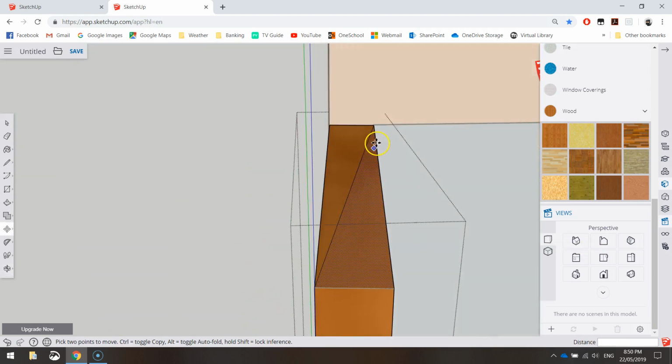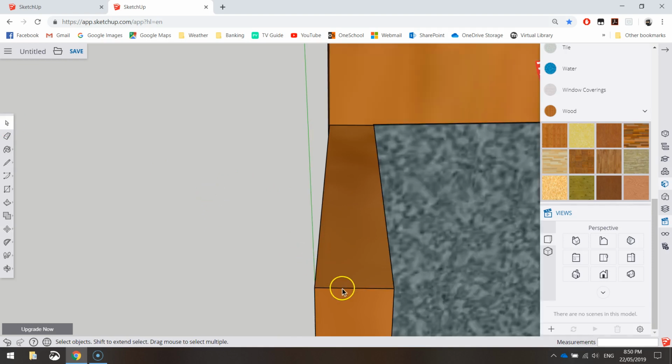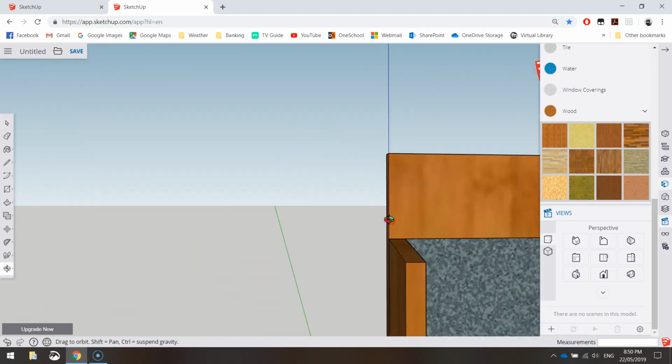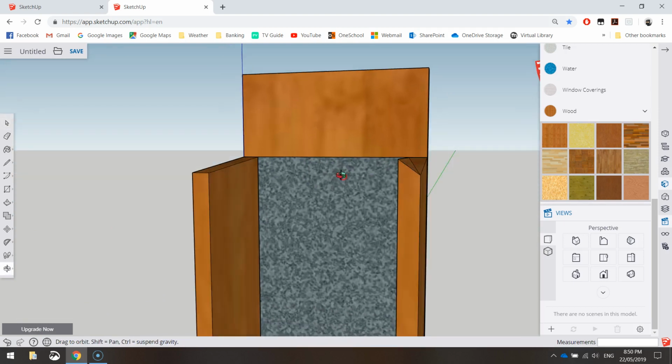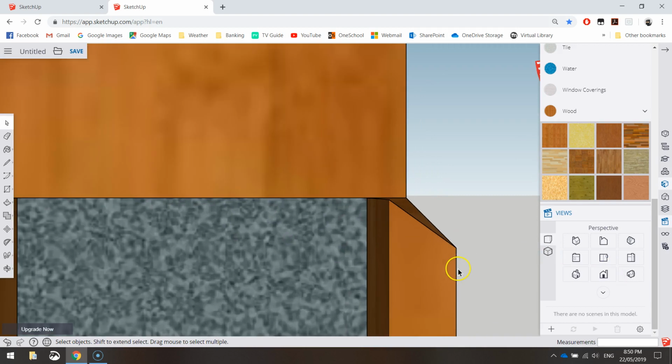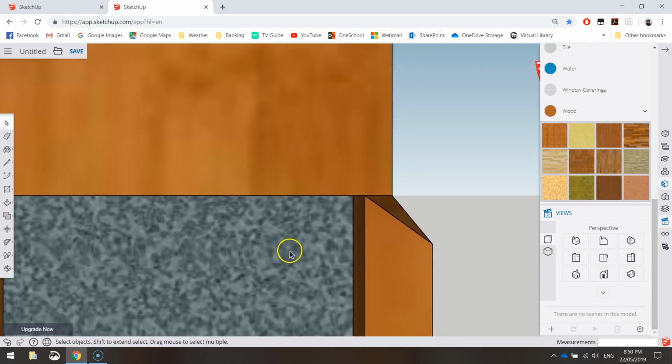There will be a black line running across the top of that you can just click on with your arrow and press delete. Don't need that. Click outside of your shape. If you want, you can click on this black line and delete it. And we've now got that angled wall looking good. So we'll repeat that on the other side. Okay, so go to the front view, zoom in, and just either double click on it now, or actually I'll just draw a line first. Straight across and connects over there.